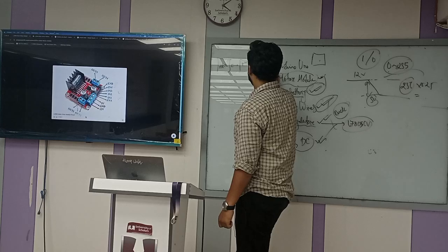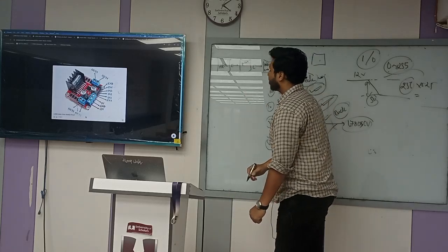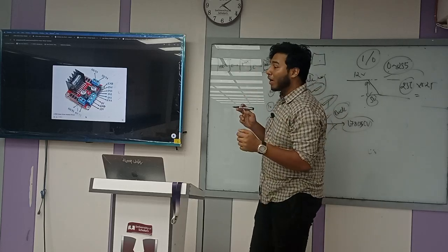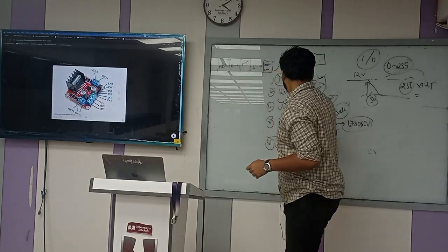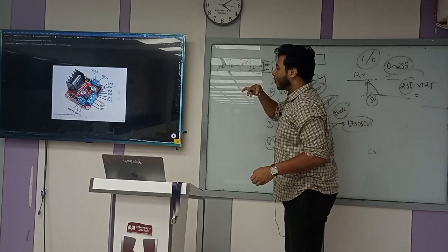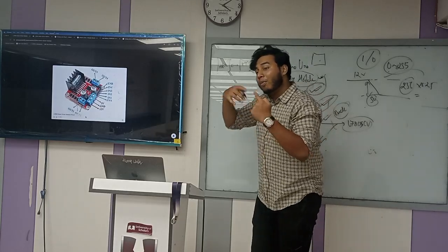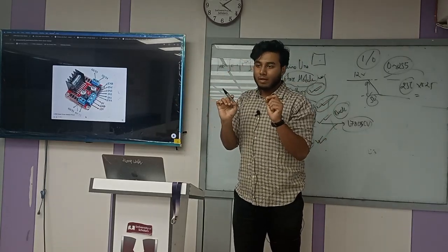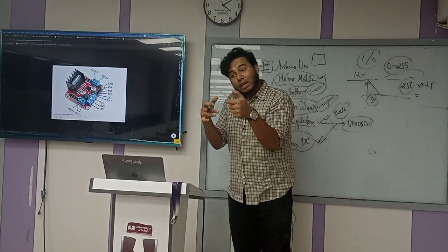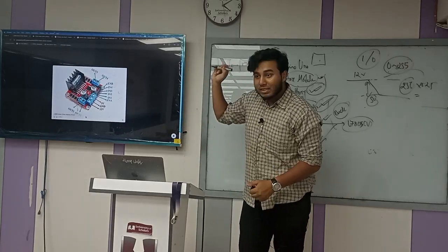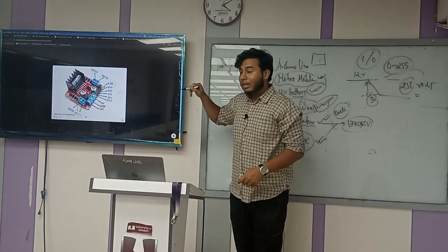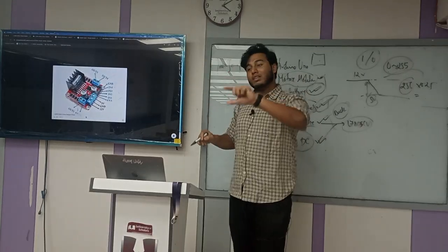Uno. So these motor modules have to be connected with the Arduino, to make sure the codes are passed through the jumper wires, to ensure that the PWM operates as per your coding. If you have mentioned in the code that the Arduino analog value is 64, then the motor module must know, yes, it is 64, and according to that code it has to operate the motors.